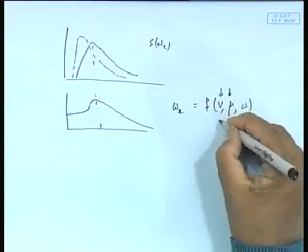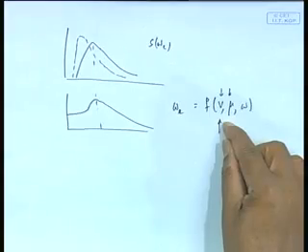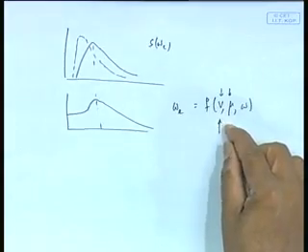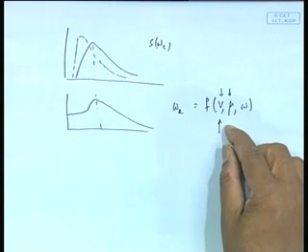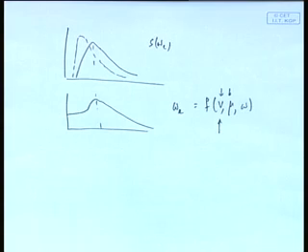So, typically what I do is basically, see, I cannot increase V because typically I am running at the full V. So, I can decrease V. I can also change mu marginally. I do not change mu typically very hard because, as I keep telling, if I want to go A to B, I do not want to end up going to C by changing my heading. Okay. So, what I do, of course, I make slight change, but primarily I reduce V, and this is what is known as voluntary speed reduction.